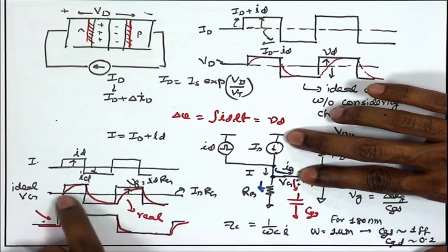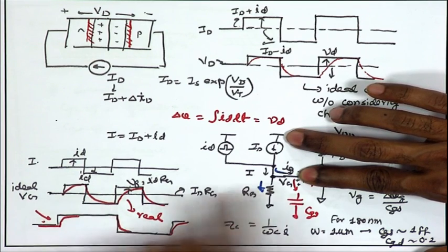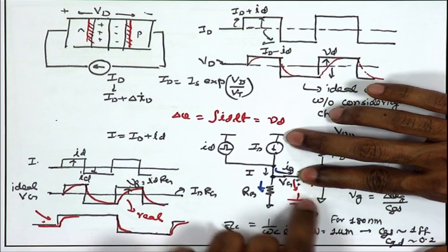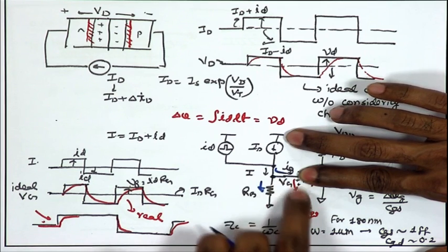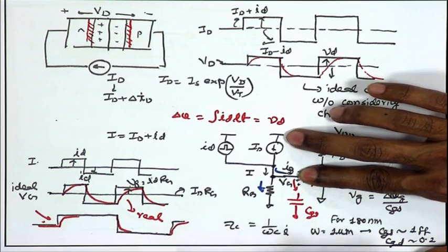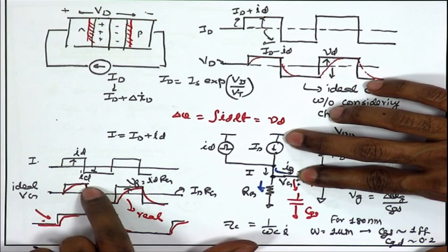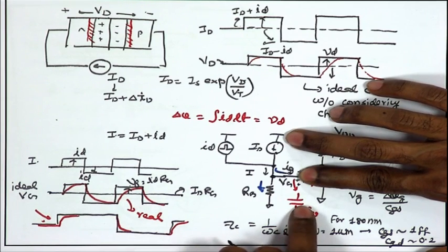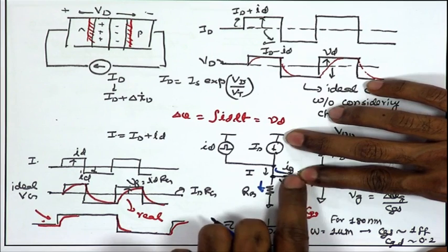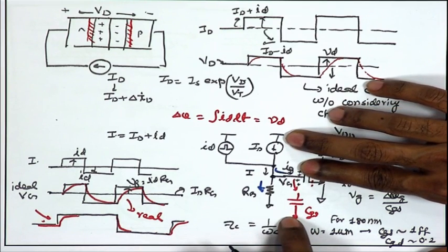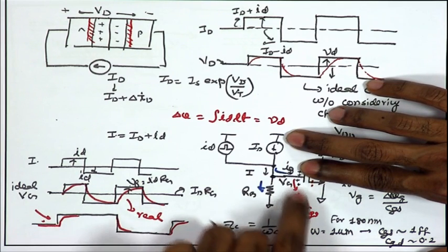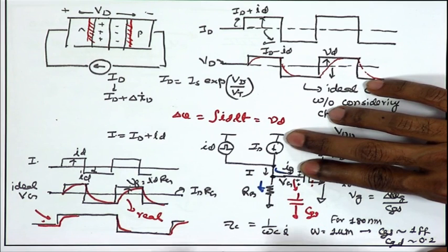So, you will take some finite amount of time to increase the voltage across this capacitor by integrating the small current flowing into the capacitor for a finite duration, then only the voltage of the capacitor will gradually rise and reach the final value. If the CGS is larger and larger, if this effective capacitance between this point and ground is larger and larger, you are going to take more and more time to integrate the current and cause the same voltage increase.